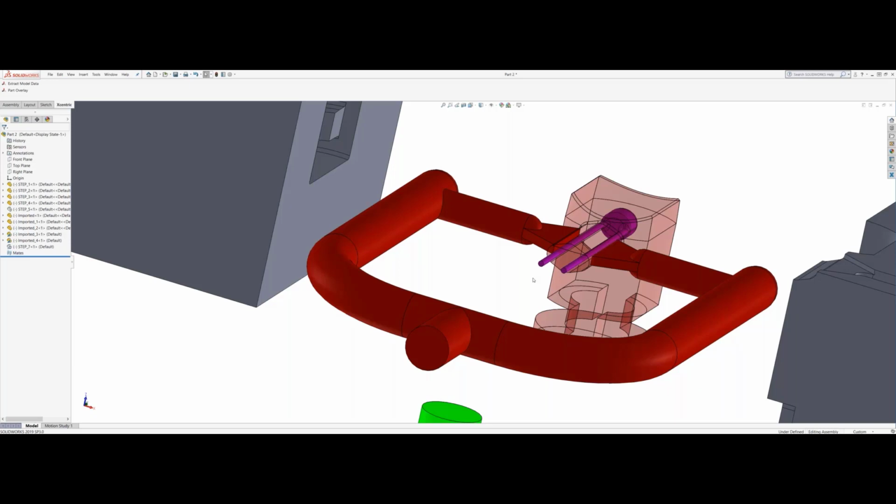And this part is pretty thick and chunky, as you can see. I forgot the exact material. I believe it was some special TPU with some fillers. But it's really going to depend on the material, and each material is going to have its own wall thickness range that it likes. Typically 40 to 60 thousandths. This part by itself was roughly maybe 3/4 of an inch overall in height, from here down to here. So it wasn't a small part.